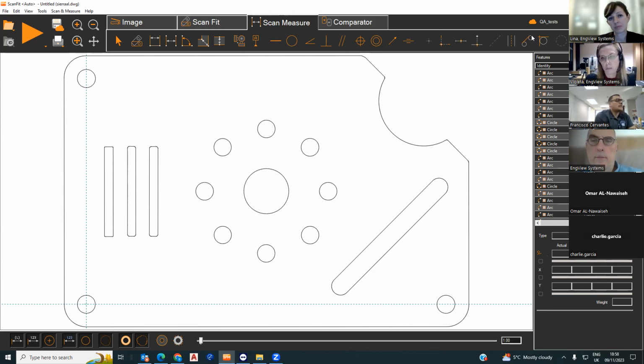No option. The only thing you should do is remove the burrs and turnings by file or automatic belt, if your tolerances are very tight, but it's not scratchable and fragile for the measurements. The only thing you should watch out for is that when you clean burrs and turnings, the edges of the profile shouldn't be rounded. Yeah, sometimes those automatic deburring machines round the edges.